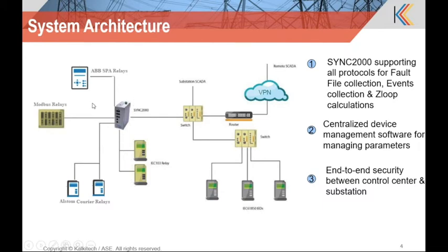And apart from live data collection and fault file collection, this can also collect events available in all these relays, and we can convert these events into a CSV file and transfer it along with the COMTRADE data to the central system. So that is also available.